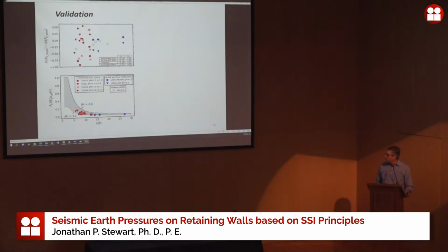What is helpful in a situation like this, because you have many different beta H's, is to take the beta H for any individual test, run the calculation, and calculate a residual. So you take your measured one, you subtract what you would predict using the method I just described, and that's a residual. We take the difference of the logs. So 0 would mean a perfect prediction. This would mean that we're under-predicting. This would mean that we're over-predicting.